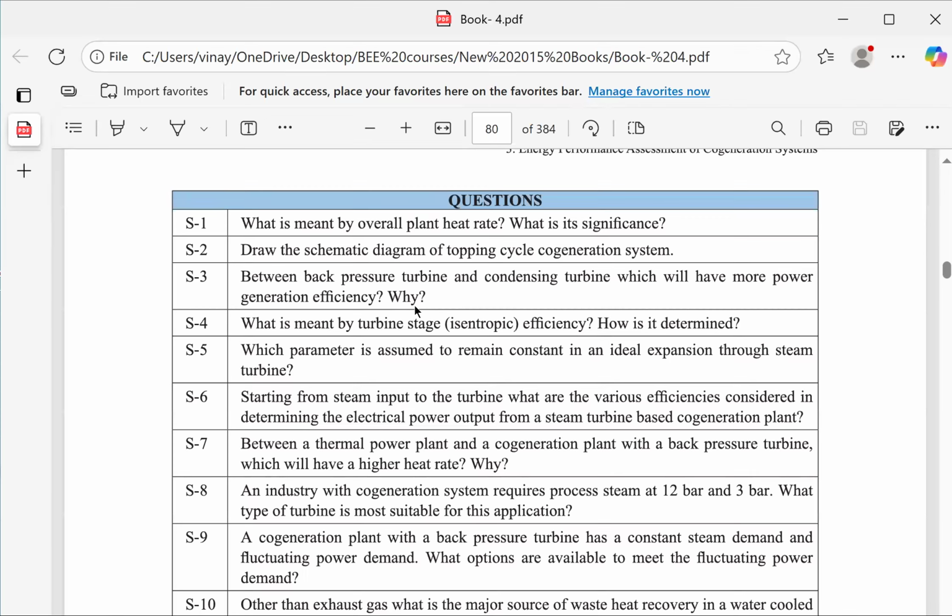And when they have asked me the reason, I will say the pressure steam is allowed to expand from the highest pressure to negative pressure. It's a long range through which it is expanded and therefore the mechanical work done by the turbine is more in the case of a condensing turbine, whereas a back pressure turbine gives more work in heat to the process.